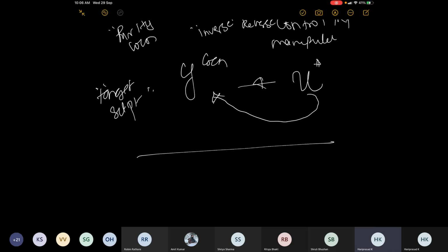Okay, so let's say you wanted to control a reactor. This is a reactor. There is a feed in, and there is a product out. There may be a stirrer inside, and you may be heating it. So this may be jacketed, and the jacket would have a heating fluid or cooling fluid, which would be recirculated by means of a pump, and so on and so forth.